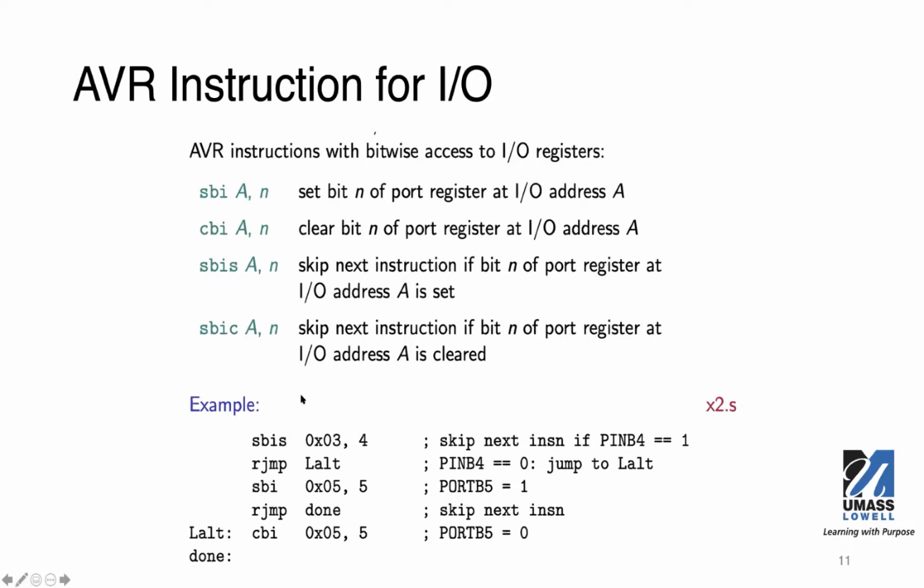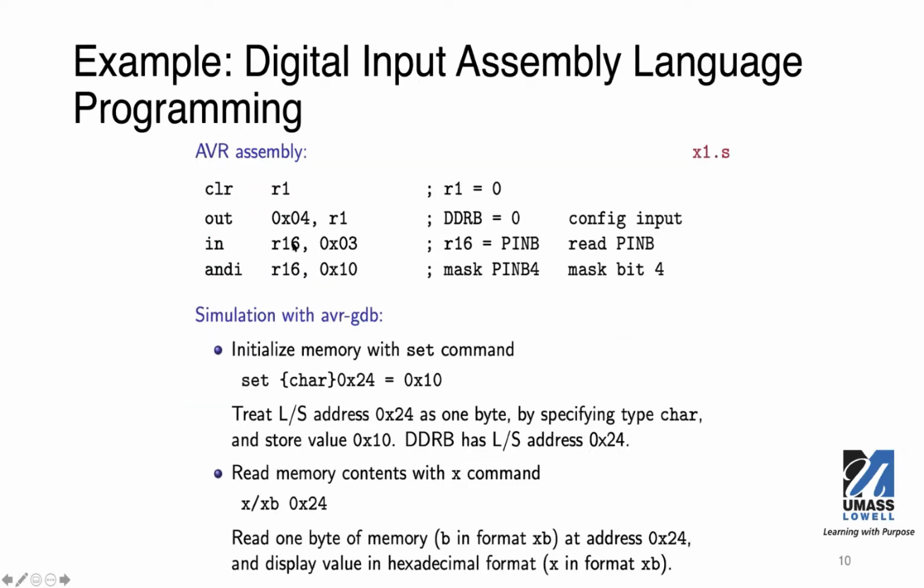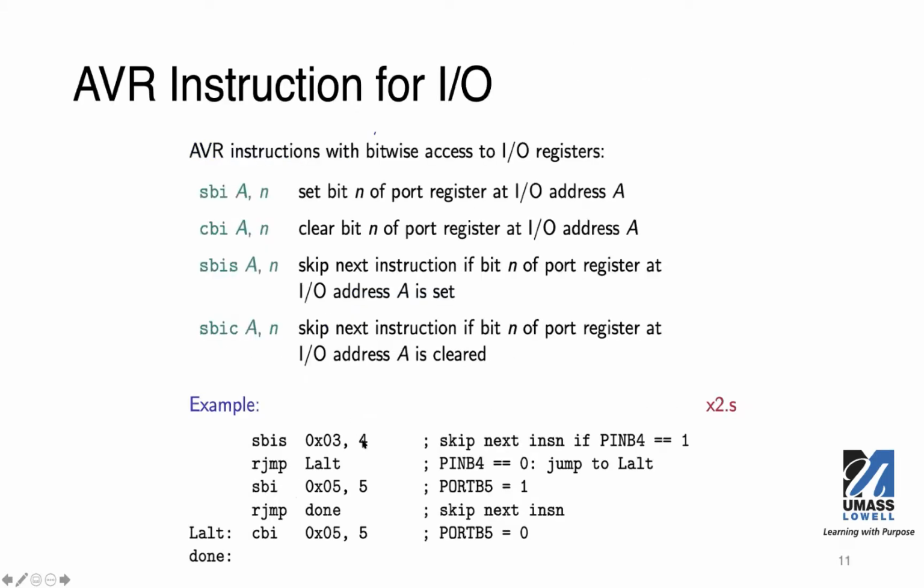Okay, so what we had earlier, let's see. Remember that we read the value from this PINB register into R16. Instead of reading the value into a general purpose register, we can just check the value on that bit.